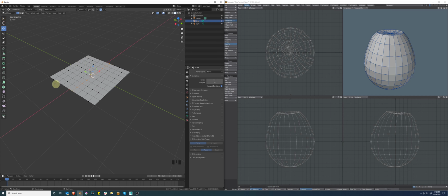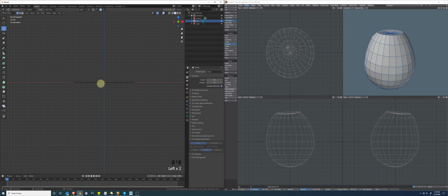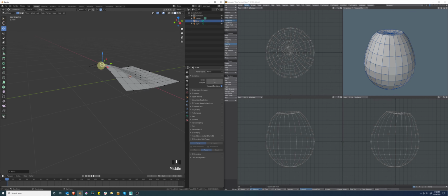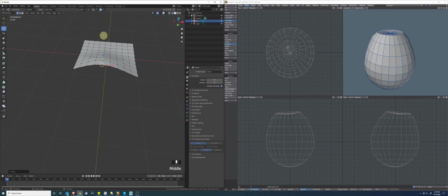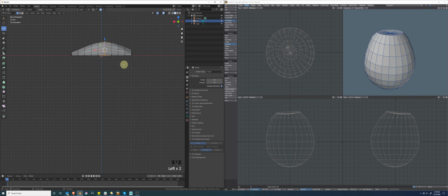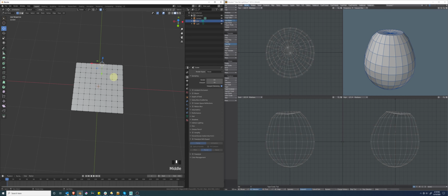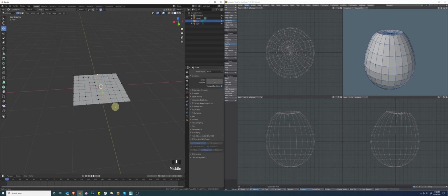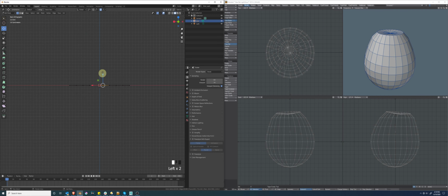If I'm looking down one of the orthographic views, however, let's say for example, I look down the y-axis and I want to impact this vertex here. If I were to click that and drag up, really, I'm just lifting that one vertex and everything begins to fall off, which then means I'm going to have to select all of the vertices and then come back to that viewport again, let's say the Y viewport, and make the adjustment from there. Okay, so there's an easier way to do this than coming through and selecting every single one of these vertices and then looking back down the axis again and making your change.